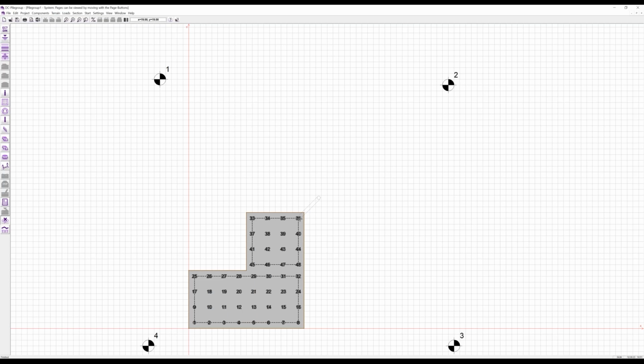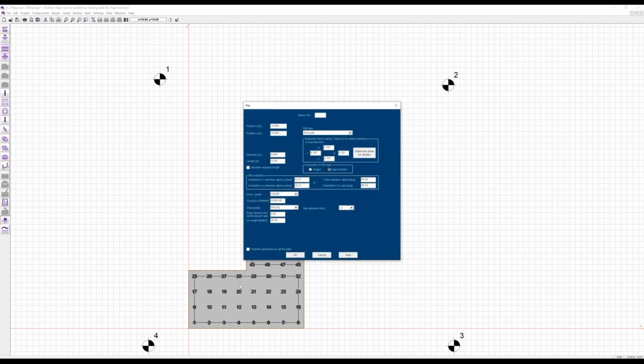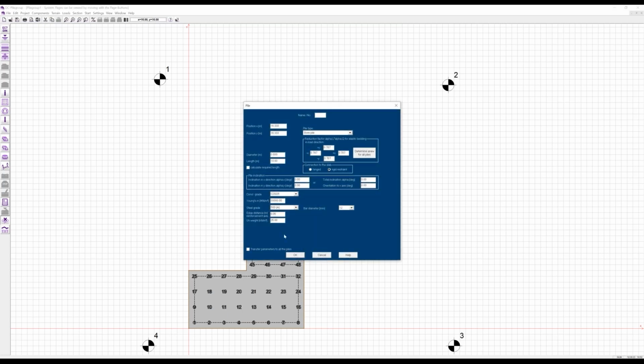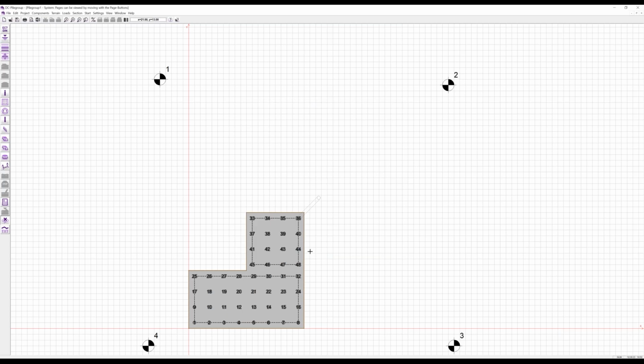And what is calculated automatically if you have the grid entered before is a reduction factor for the elastic bedding for the horizontal load of the piles. So if a pile is a pile at the edge of a grid, it may have more elastic bedding, more support, or more resistance than a pile in the center of a grid. So depending on the load direction, to plus and minus X direction or plus and minus Y direction, the program tries to define the correct reduction factors, and this is used for the horizontal loads.